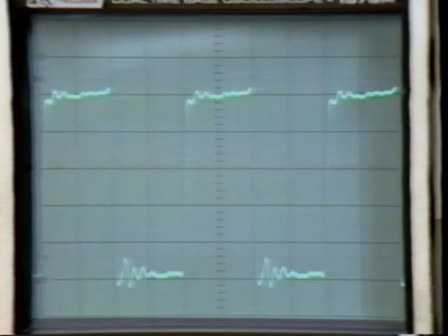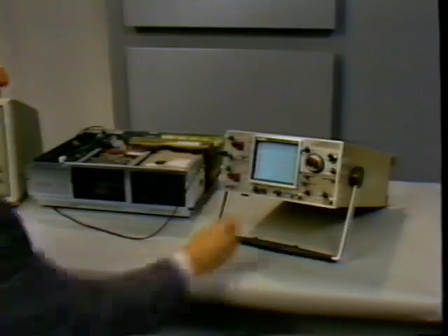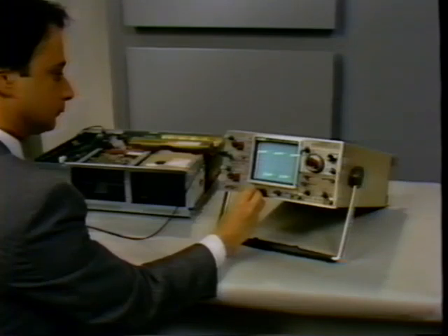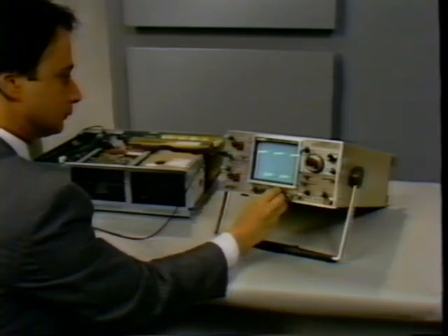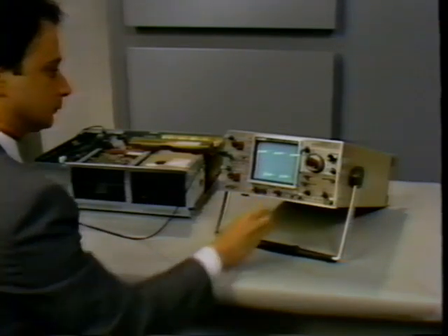If you have selected Auto Trigger, you will now see a display of some type. If either the volts or time per division requires correction, fix them now. The final step in observing a signal is to produce a stable picture by synchronizing the sweep with the signal being displayed.